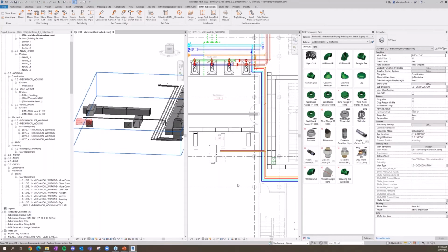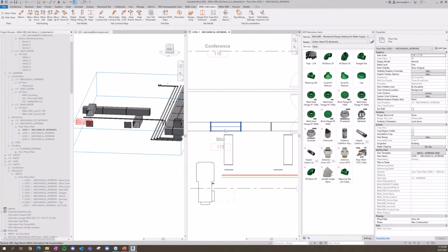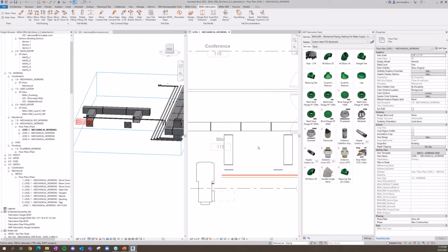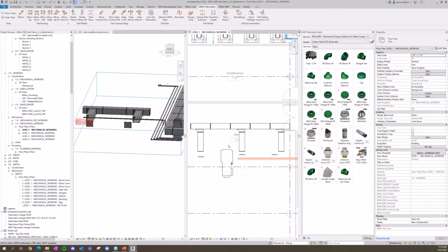And again, these things work in 2D or 3D. So if I want to align branch in 2D, I could do that and just adjust these heights so everything matches. I could then do a very quick trim extend to bring these elements together, because we're just trying to leverage the commands that BIMrx or Revit already has for us.